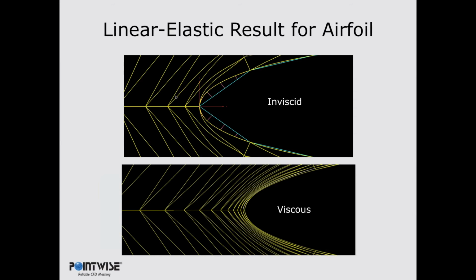This slide shows the result of elevating two different meshes to the surface of an airfoil. The top one is an inviscid type spacing, so larger elements, but it's a fourth order polynomial that's being used. So you can see near the leading edge there is quite a large displacement of the surface, and the curvature of the mesh is evident in the interior. And then the bottom image is a highly packed mesh, and you can see that it's still successful at deforming the mesh and generating valid elements in this case.